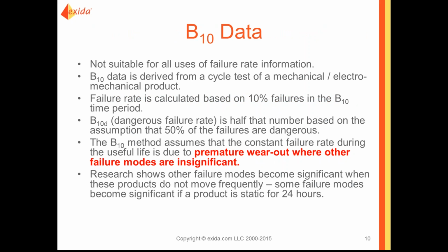B10 data is not suitable for all uses of failure rate data. B10 is basically back calculated from life tests of components, mechanical or electromechanical. Based on an analysis of the failures, usually per cycles, it extrapolates back a failure rate. Now that failure rate can be useful if the device is in a continuous demand or a high demand application